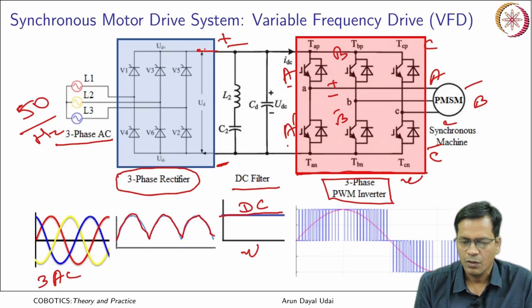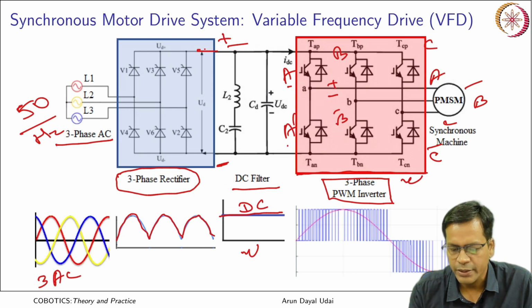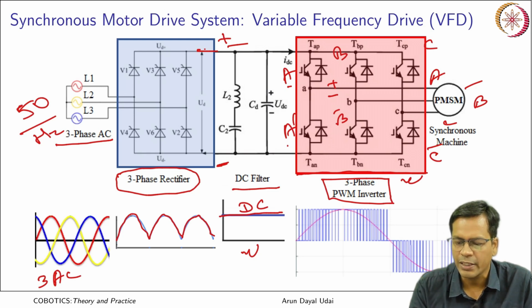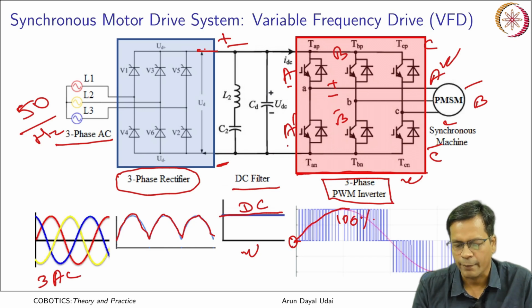That means in order to regulate the level of voltage on the positive side of A, you create a PWM with 0 to 100% duty cycle, so that you see an equivalent voltage rise in the A wire. Let us say it is A only.